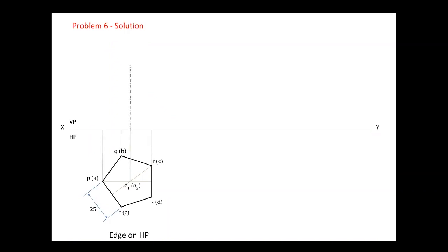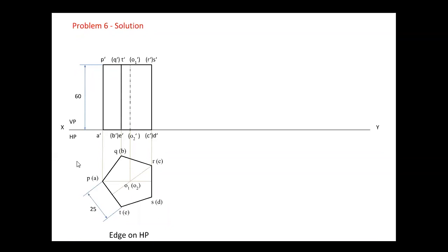Then I'm going to draw the axis line, which will be the chain line. Chain line will be one large and one small, one large and one small, of the axis length given. The axis is the imaginary line from the midpoint of the top base to the midpoint of the bottom base. So I'm going to dimension it in the given problem. The length of the axis is given as 60, so I'm going to dimension it. Then naming is done.